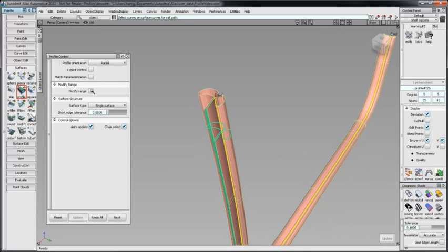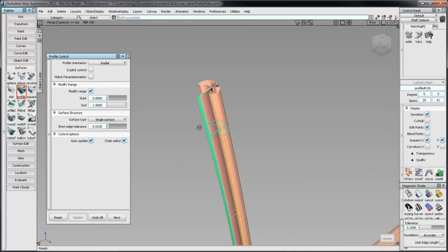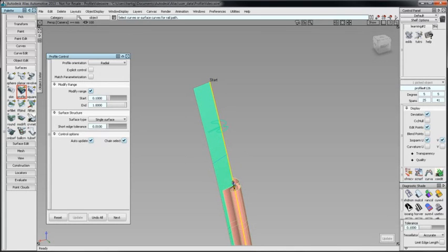Modify range allows adjustment to the start and end of the profile surface. A value can be entered, or the start and end sliders can be placed visually, or the sliders will snap to the red X's along the rail at curves on surface and isoparms.